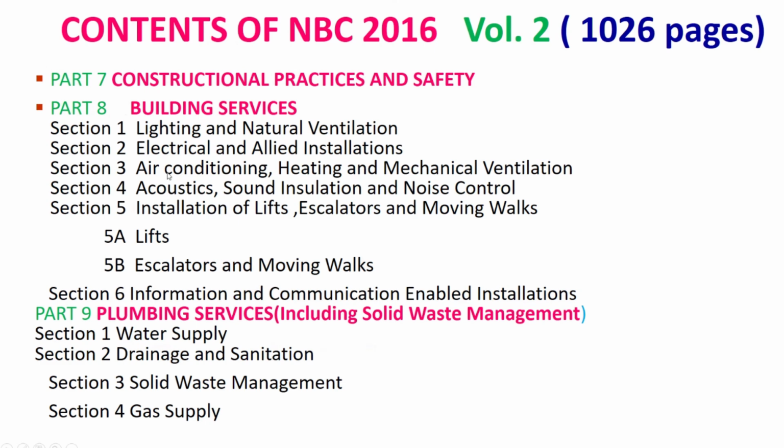फॉर अ कॉम्पैक्ट बिल्डिंग साइट कवरिंग एन एरिया ऑफ अबाउट 0.4 हेक्टेयर. 0.4 हेक्टेयर बोले तो कितना स्क्वायर मीटर हो गया, क्यों भाई कितना हो गया 0.4 हेक्टेयर. हाँ 4,000 स्क्वायर मीटर. So suppose it is 4,000 square meters. So what we are supposed to do, we have to take one borehole or the trial pit in each corner and one in the center, which is required to be taken.